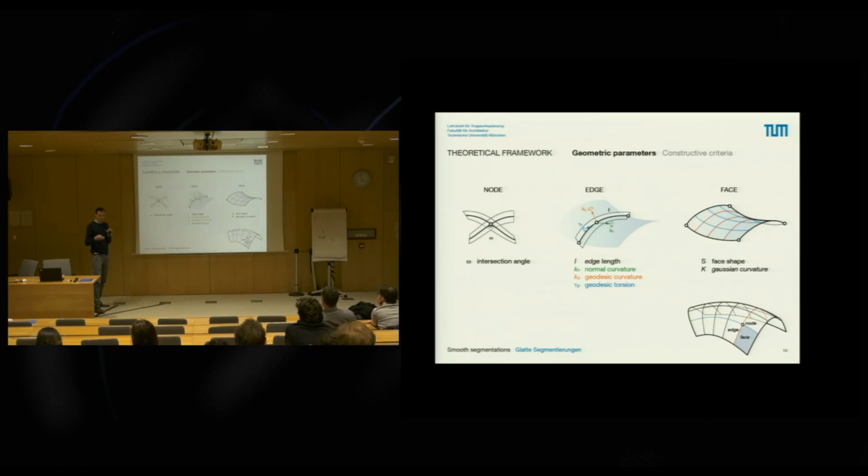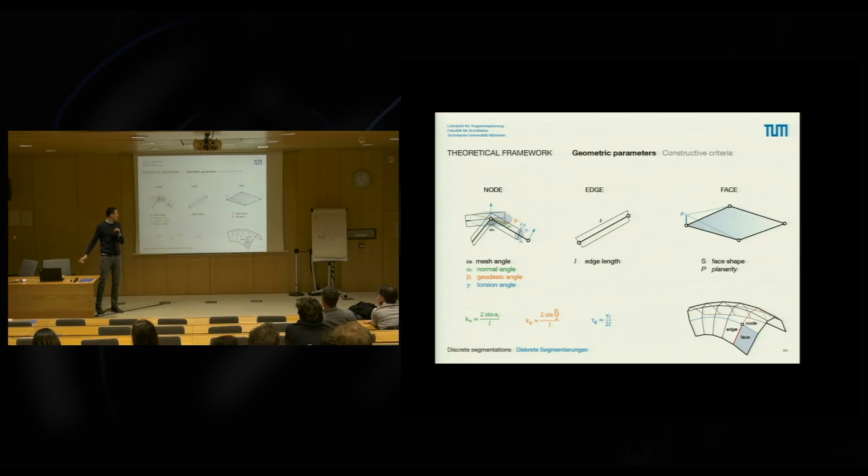And the beauty is, when you look at discrete segmentations, you also get three extra angles. And they're not any angles, they're directly related to the curvatures which I just showed you. You can actually calculate from one to the other if you have to. So if you imagine a joint, the normal angle, I called them the same name now, would be this kink angle that you get at a discretized mesh.